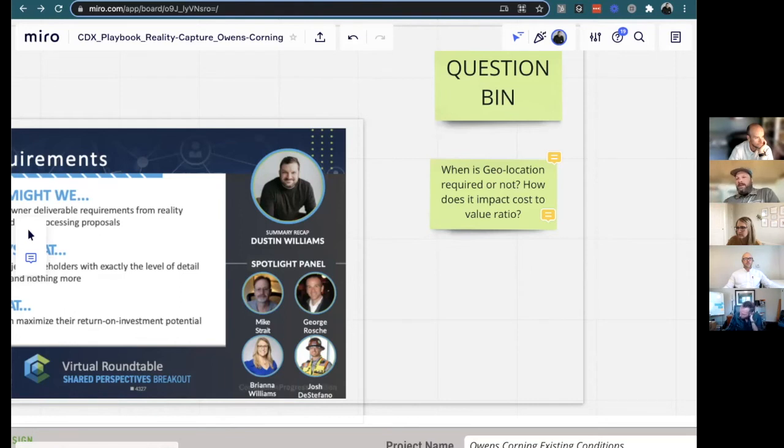I mean, you can have a model at 0, 0. That 0, 0 is referencing a geospatial coordinate, a global coordinate system. I see it a lot. I will say that what I've been seeing, and I would love to hear what others are seeing, is that all the projects that are starting now seem to be working in real world coordinates for their models that are getting published out to all the stakeholders.